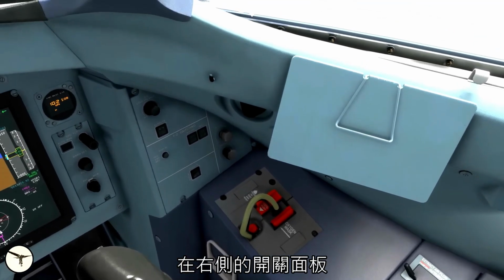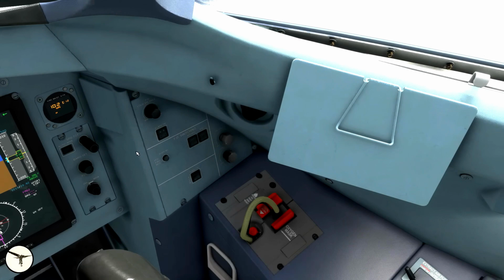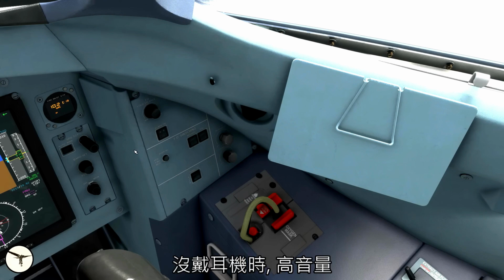On the right hand switching panel we have controls for reading light and console light. You set as required. There shall be no alert lights. The loudspeaker is set as required. Without headset, you set high volume. When you wear headset, low volume.